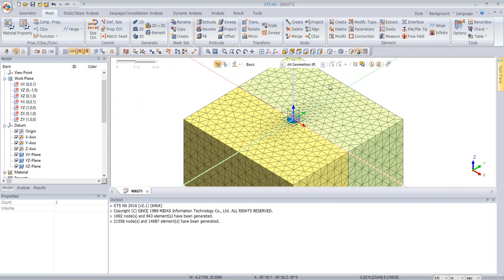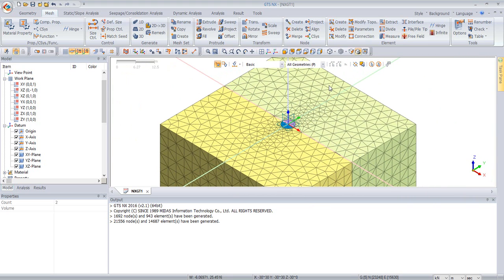Well, that's another difference with the Plaxis software. They had to use a helper object in between, an additional geometry with a specific mesh size, just so they can get these connections between the inner and the outer layers, whereas we don't have to worry about that. The program is very good about connecting automatically these gradual changes, these different sizes of elements between sets.